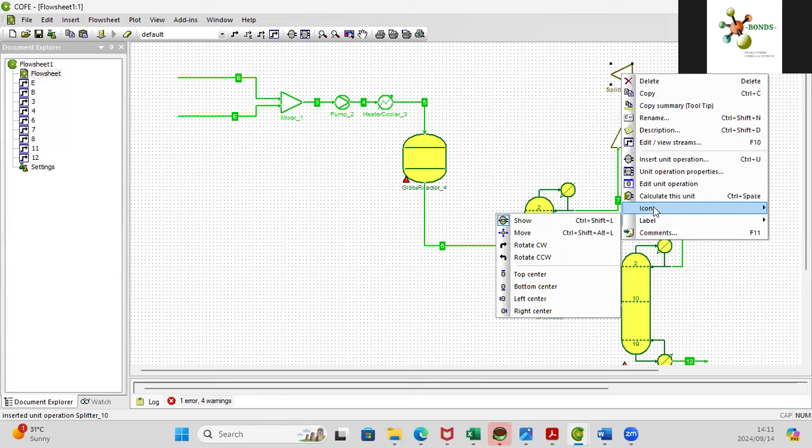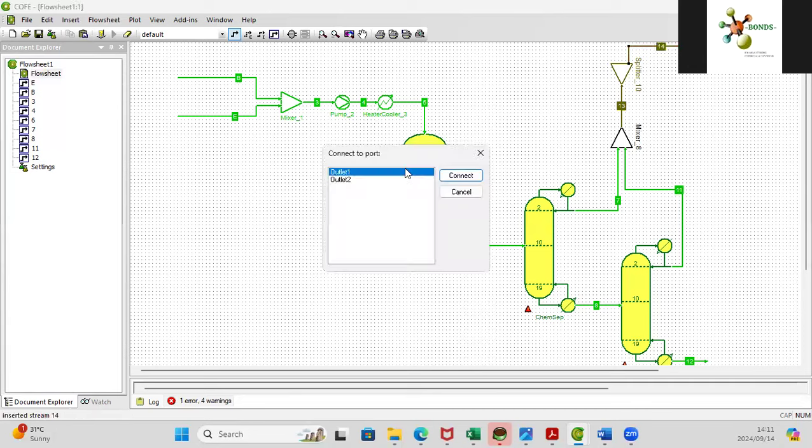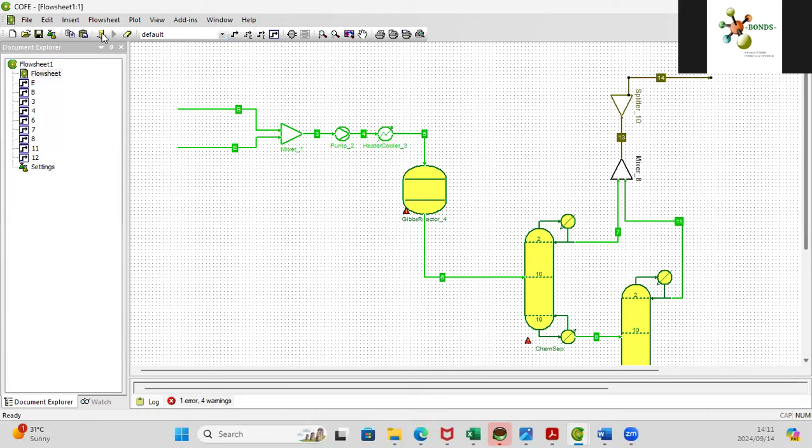So do not throw out your background knowledge in chemical engineering when you're doing this kind of design work. It plays a critical role. So you do need to remember that. Some of these considerations are quite common sense. The bigger your stream, obviously, the bigger your pipes, the bigger your equipment, therefore the more costly. And as the design engineer, your job is to design something that will be cost effective.